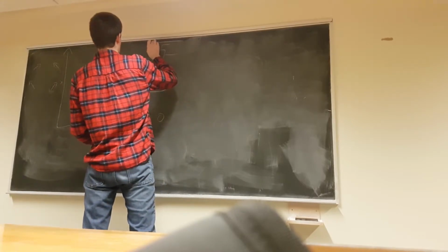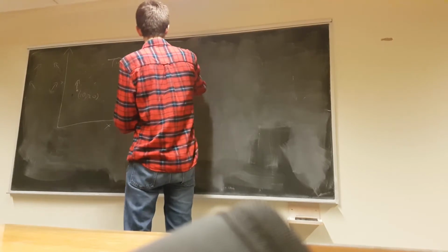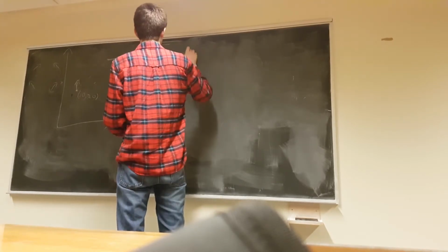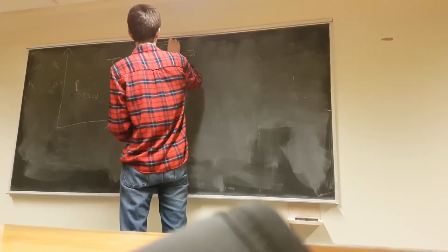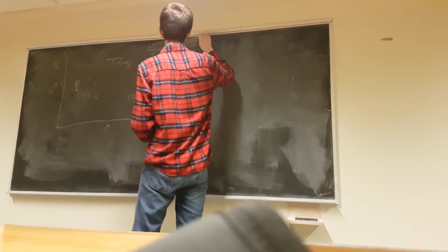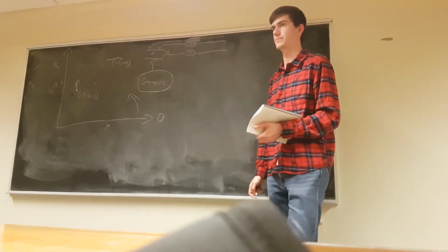Say this is x, this is y, and this is theta. And then, what can we do? We can run, I'm not going to write in the targets here, but we can run a PID loop. My apologies for that being small, but believe me, they all say PID in them. We can run a PID loop on each of them, right?